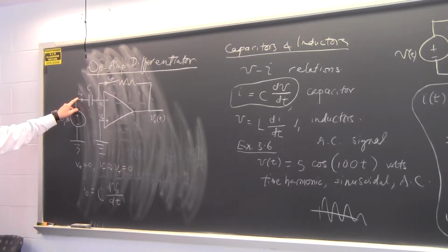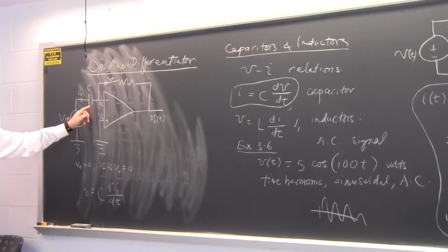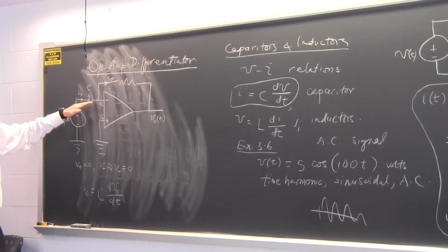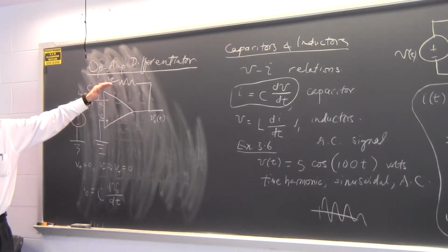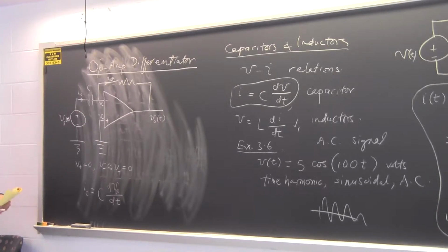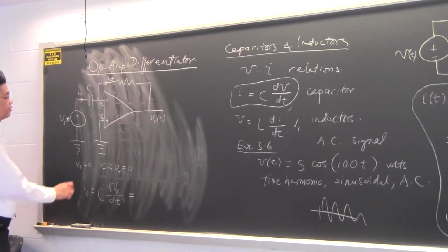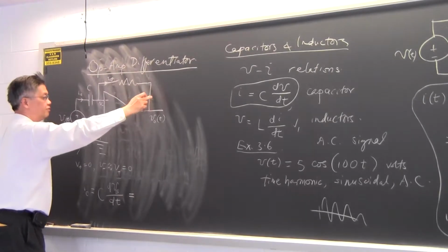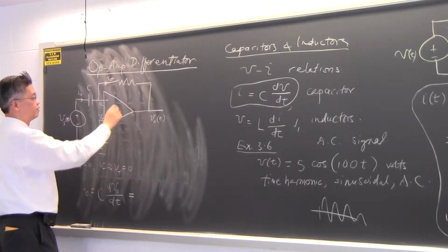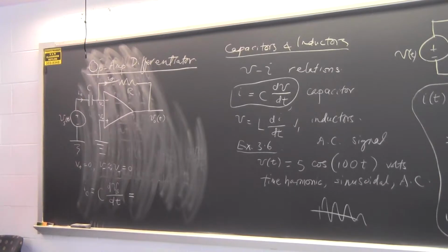They're very close to each other, right? Because nothing goes into op-amps. Op-amps are high input impedance devices, almost no current can go into them. So this current will veer its way up and become IF. Okay? So hence this current IC is also equal to this voltage minus this voltage divided by the resistor R. Okay?